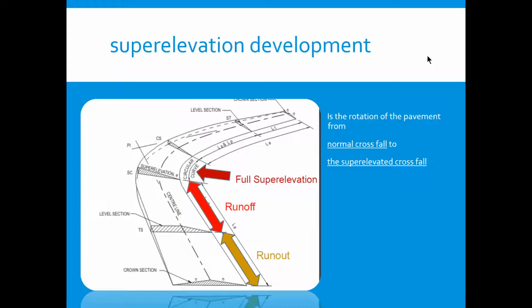Superelevation should be developed by rotating the road about an axis of rotation. The adopted position of the axis depends on the type of road, the total width of road cross-section, and the terrain. On the single carriageway, major urban road, the cross-section may be rotated about the center line.